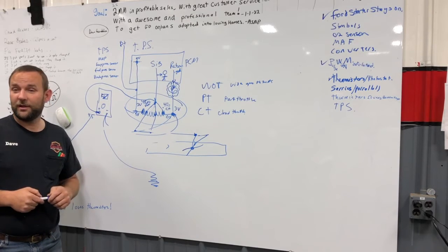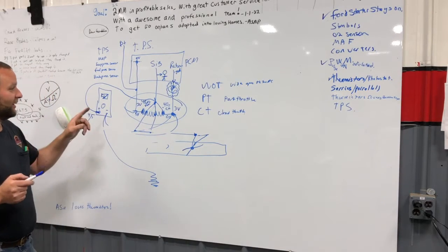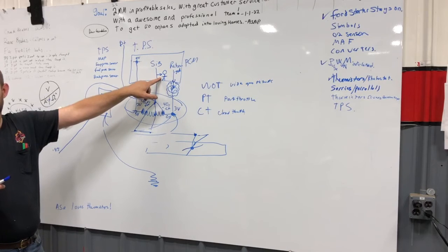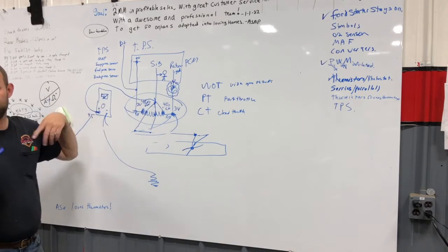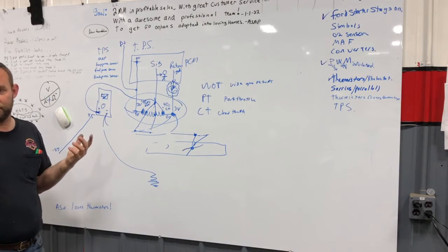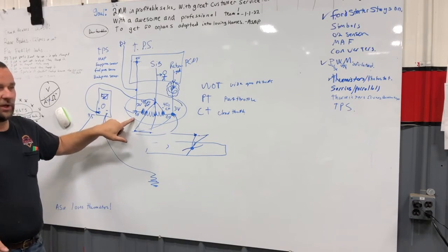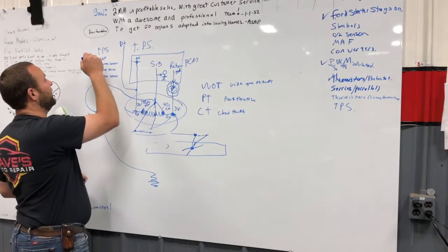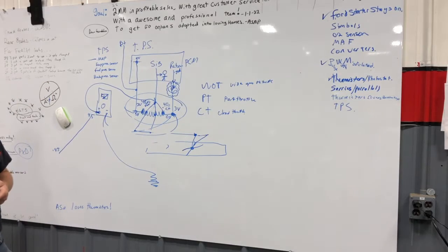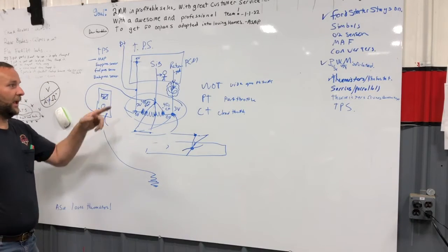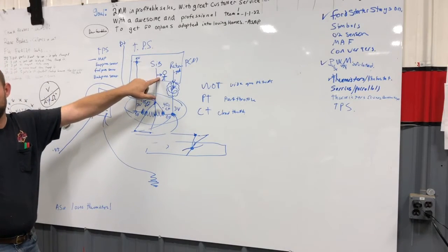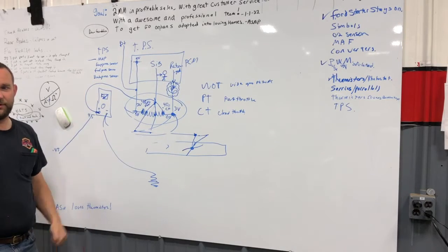Or, this is the cool part, the comparator will set a rationality code, like, I know this ain't rational. It says I'm wide open throttle, but then my MAP sensor says I'm at idle. He has to literally make a decision which one he's going to believe. Ignore one and use the other.